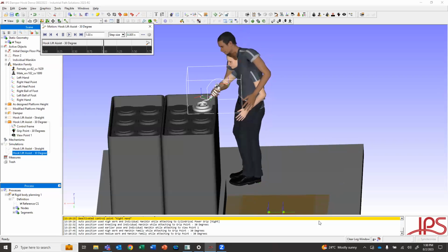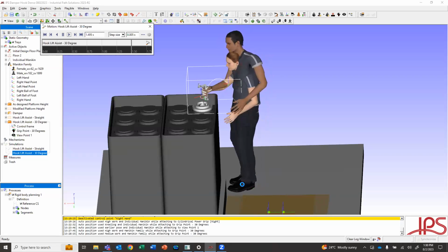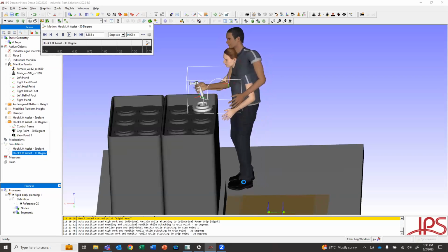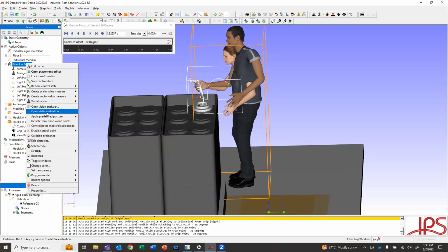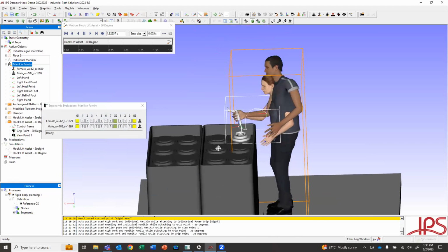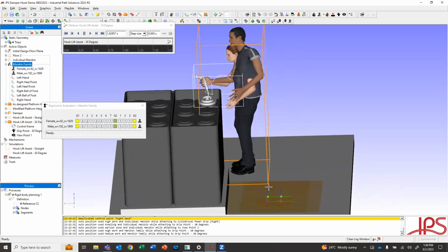And see how that change in floor height, for example, if I were to put a platform there, how that would impact the job and the postures associated with these two individuals. So if I were to take this and then go into the same static evaluation we looked at before, we can now see that's reduced for both of the individuals there. So we know we've improved this work setup simply by raising the height of the surface they are standing on.